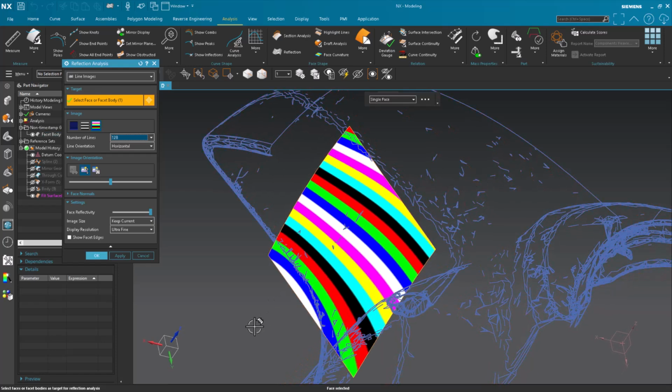Do we want to see that as part of the surface? And again, this is just a little section. If I were to do that whole side, I'd end up with a far more exaggerated version of what you're seeing here. You can see how these contours flow nicely, and once you get up to about this green one, you'll notice they start flattening out as they go forward. So this is telling me that there's a little distortion in that surface.